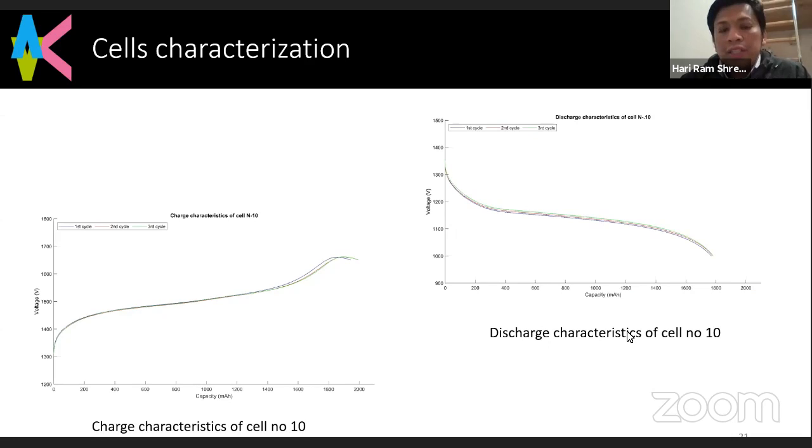Cell matching is important. So DC impedance is a very important part. All this process will take a result for DC impedance, so we need to make sure of the cell balancing. If you are connecting 3 cells in series, for example, a 65 milliohm cell and a 70 milliohm cell is not good.